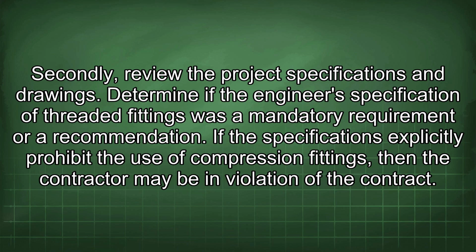Secondly, review the project specifications and drawings. Determine if the engineer's specification of threaded fittings was a mandatory requirement or a recommendation. If the specifications explicitly prohibit the use of compression fittings, then the contractor may be in violation of the contract.